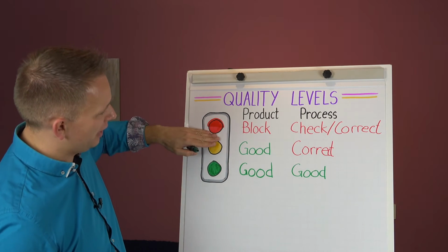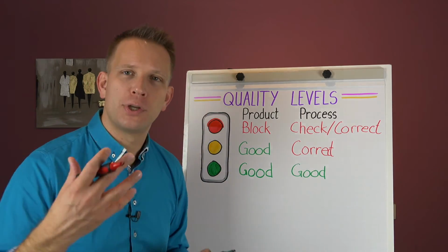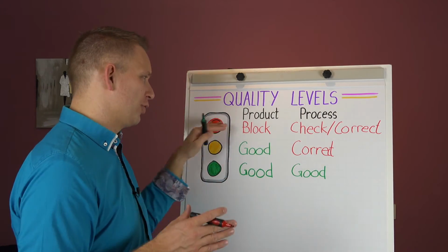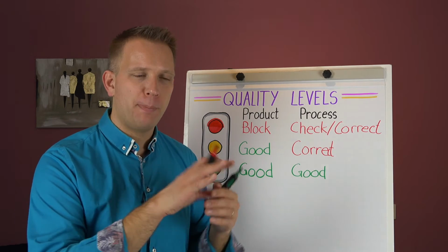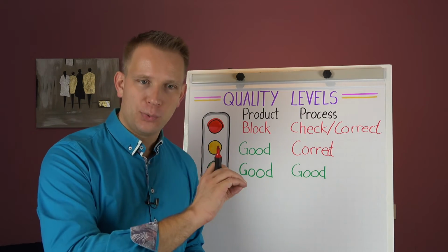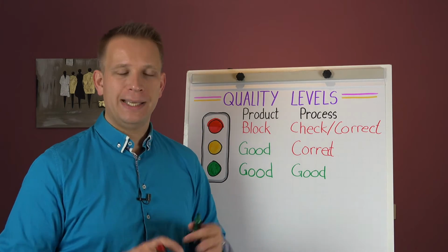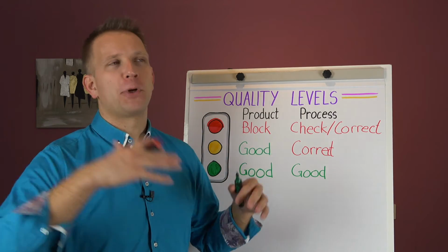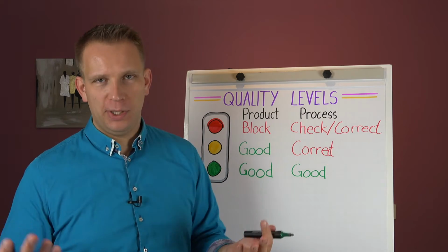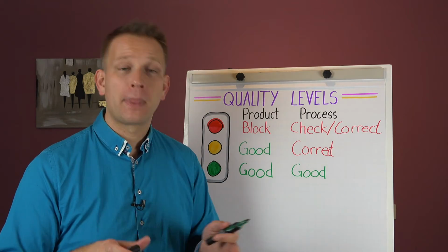Into sort of light red and dark red, where for light red, for specific conditions, so specific quality parameters that you measure up until a certain value, you have standardized ways of correcting the problem or of reworking the product, and you don't need to go to the supervisor, the quality department or whatever to really stop the process and block everything.